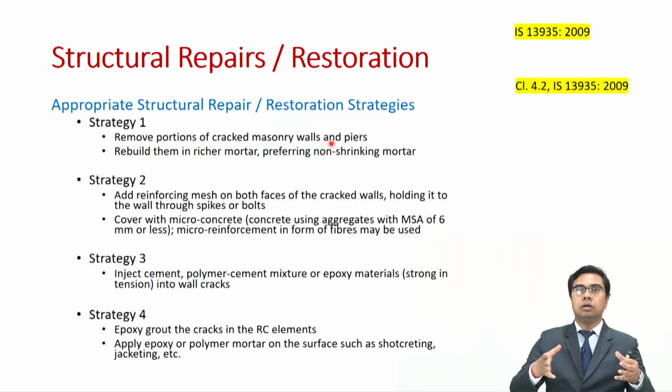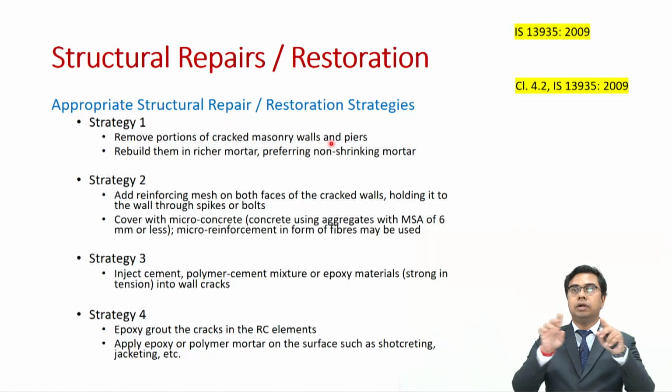You take away those masonry units and mortar where your wall has significant damage, and then you can put new masonry units and mortar and rebuild them. This time you shall be using a richer mortar, preferably non-shrinking mortar.